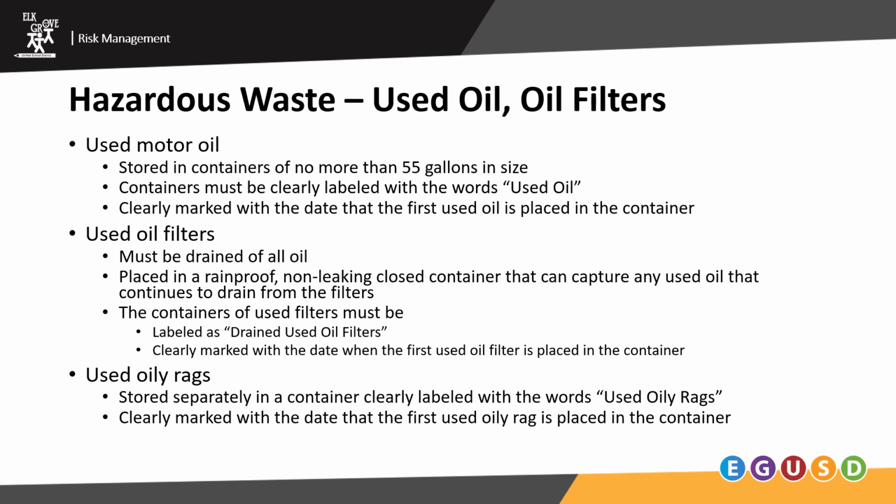Hazardous waste: used oil, oil filters. Used motor oil must be stored in containers of no more than 55 gallons in size. Containers must be clearly labeled with the words used oil, clearly marked with the date that the first used oil is placed in the container.